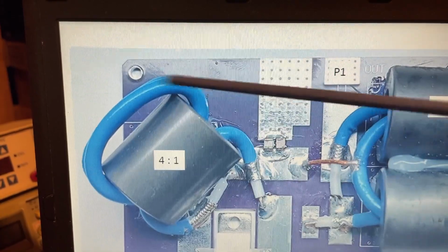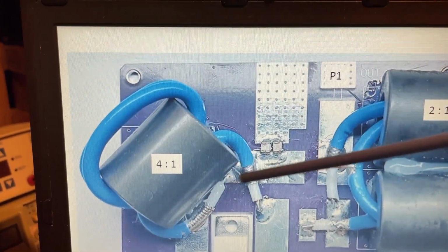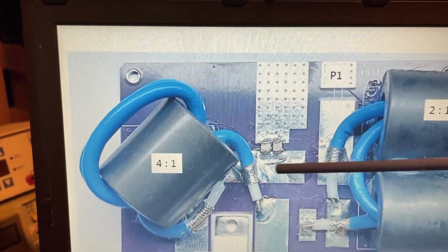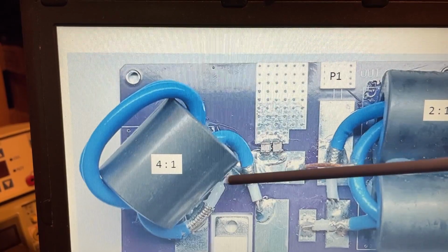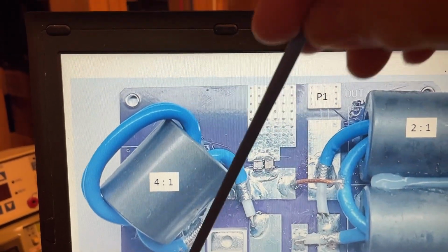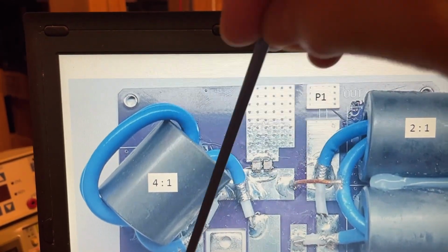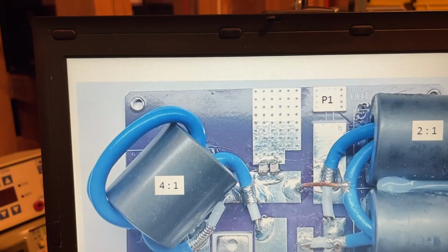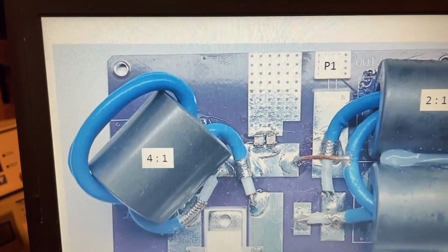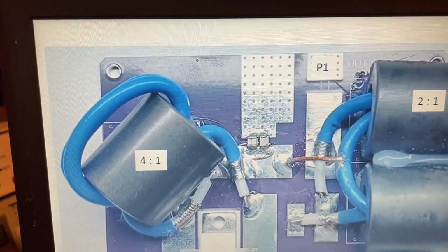So I have 2 turns of the shielding, 2 turns of the center conductor, total of 4 turns, but you see the jumper is right in the middle, so that it is center tapped. And then the outputs are across the isolation resistor. One output is the center conductor, the other output is the shielding. So you have to look at this close to understand, but they're just in series. These are just auto transformers.